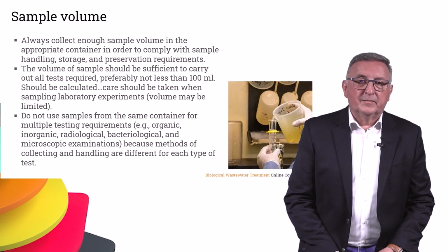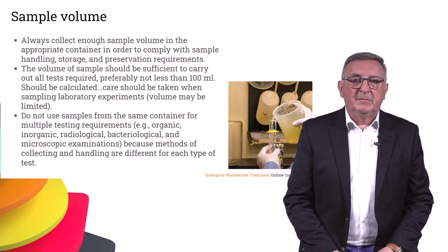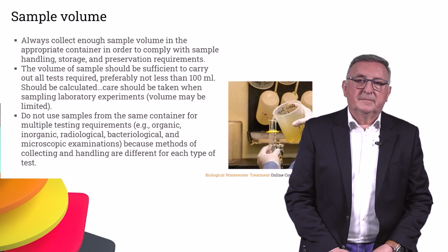Do not use samples from the same container for multiple testing requirements, for example organic, inorganic, radiological, bacteriological, and microscopic examinations, because the methods of collecting and handling are different for each type of test.